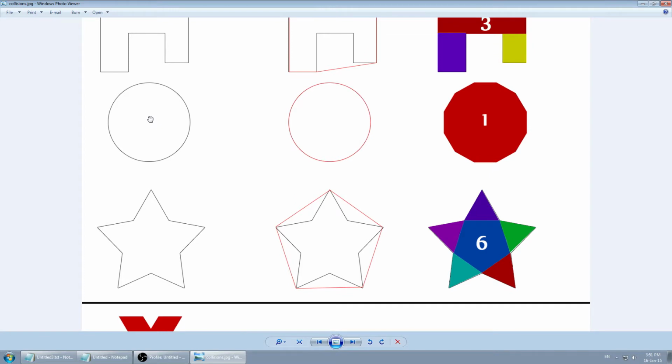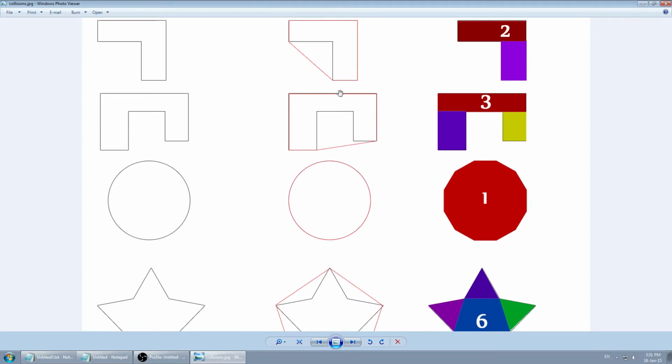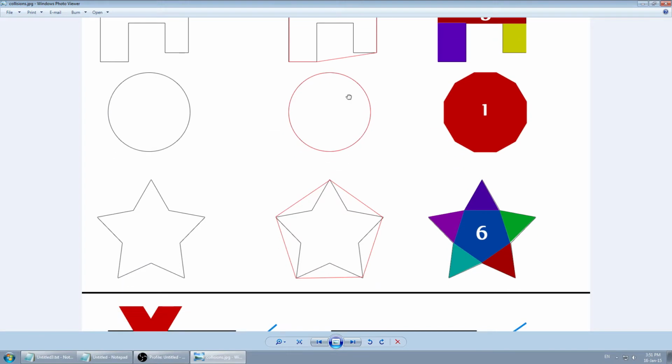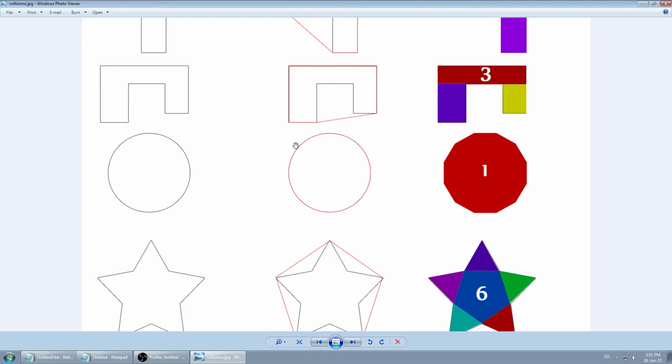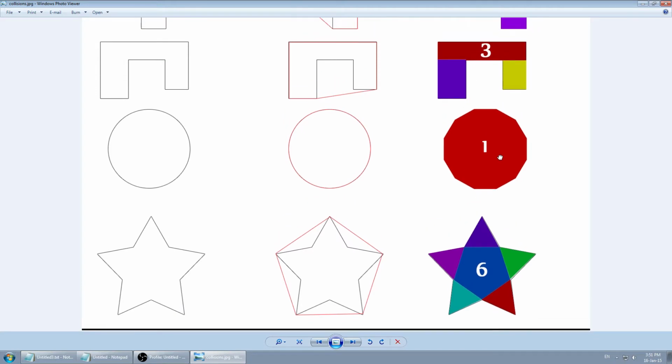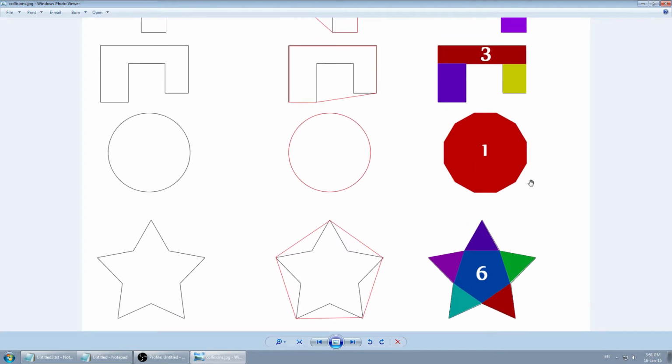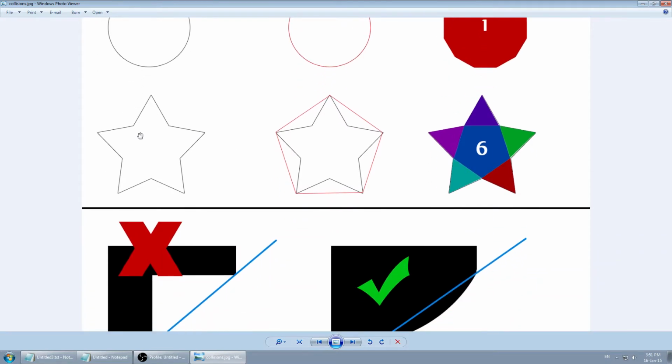Shapes like spheres and circles are going to be alright, same as with the box, because there's no cutting corners, I mean. So in order to make this collision model, you could just make a circle or use the original, but it's going to be really badly optimized. So I suggest you just make a circle with fewer segments or corners, I guess. Or for example, if you have a star-shaped model, this is going to be your automatically generated model, cutting all the corners.